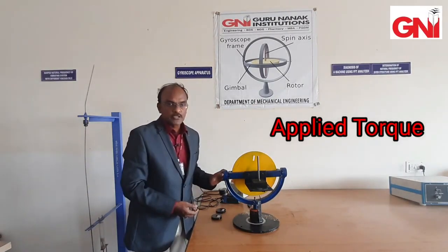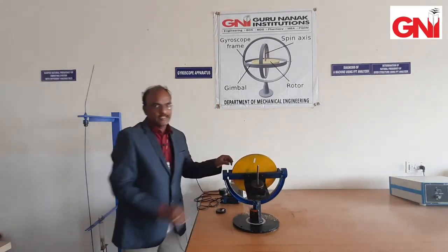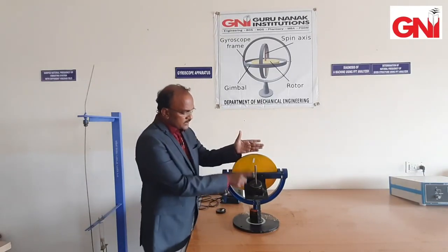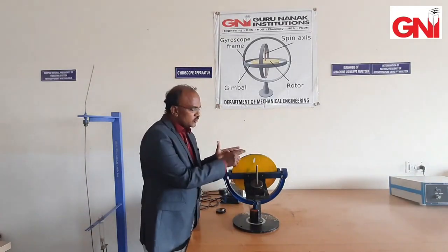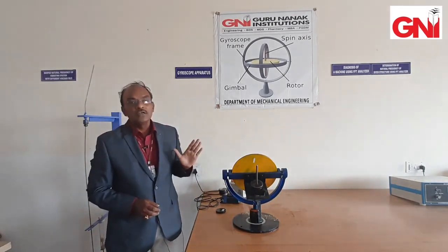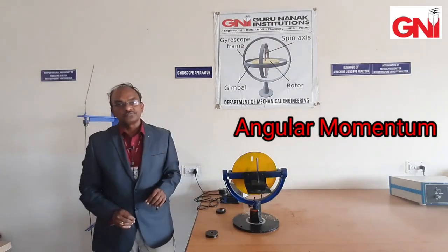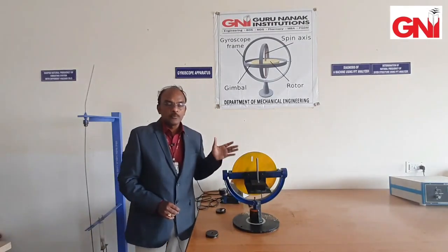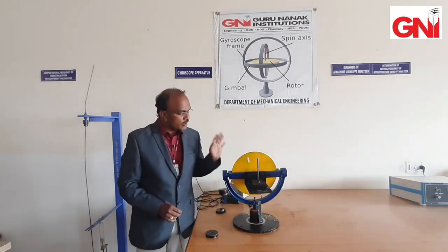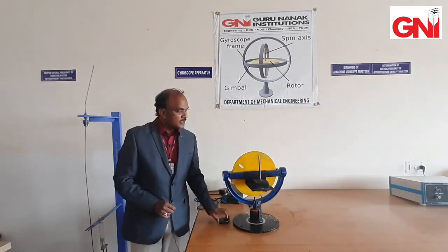Similarly, what is the applied torque? If you place some weight in the weight stud here, then due to the weight, some torque will act in this direction. The product of weight and the distance between the load and the center of the disc is called the applied torque. These are some technical terms. Similarly, what is angular momentum? It is the product of moment of inertia and angular velocity of the rotor. I into omega is called angular momentum of the rotor. So these are some technical terms used in this gyroscopic experiment.